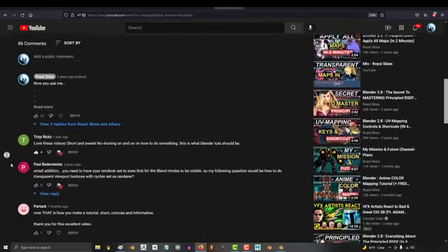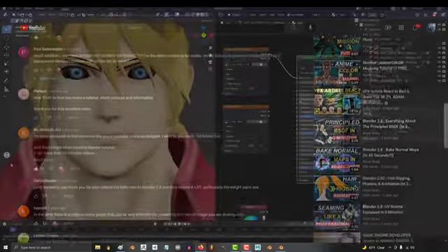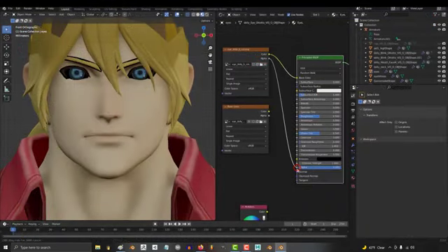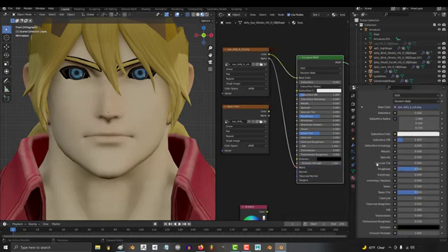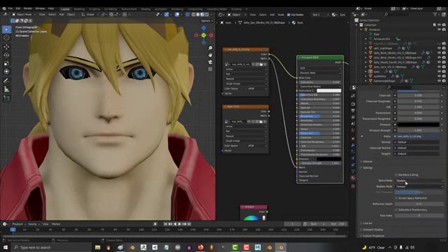And if you watch my tutorial, you'll quickly learn that when you drag a transparent texture into the transparent plug, you won't see any transparency unless you go down to the material settings, blend mode, and set it to alpha clip, alpha blend, or alpha opaque.